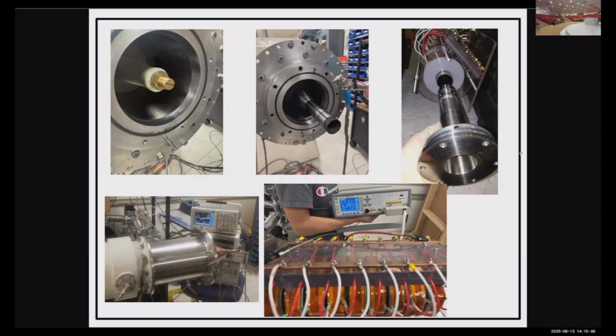we're talking about the TM0 mode. And remember, the first fundamental mode for a circular waveguide is TE11. TE11 is always there. You are interacting with the higher order mode. TE11 in real life doesn't have any axial component of electric field, because it is transverse electric. But in a slow wave structure, it's not actually TE11. It is a hybrid mode because you have corrugations. Now you have a small axial electric field component that can interact with the beam if they come at the maximum, if you shift it. So that's why you need good alignment.